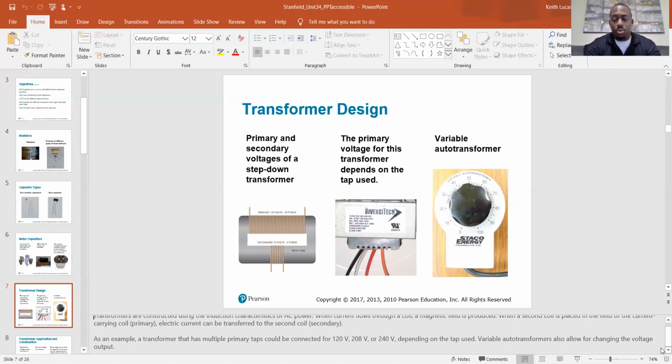But let's say you want to use that same type of transformer on a commercial package unit, and it's a 460 volt unit. Well, then you would have your white for your neutral, but then you would use your orange for your 460, and your black and your red will be separately capped off and set aside and won't be in use.